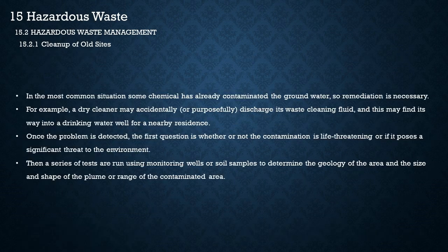In the most common situation, some chemical has already contaminated the groundwater, so remediation is necessary. For example, a dry cleaner may accidentally or purposefully discharge its waste cleaning fluid, and this may find its way into a drinking water well for a nearby residence. Once the problem is detected, the first question is whether or not the contamination is life-threatening or if it poses a significant threat to the environment. Then a series of tests are run using monitoring wells or soil samples to determine the geology of the area and the size and shape of the plume or range of the contaminated area.